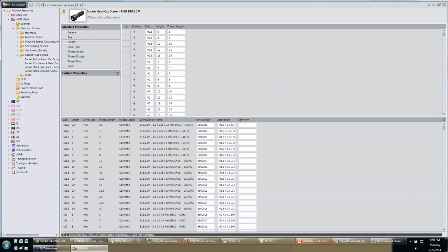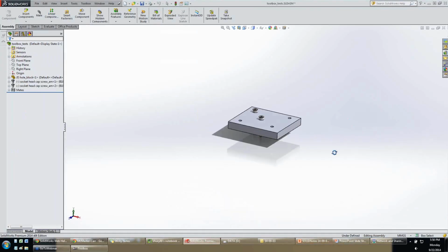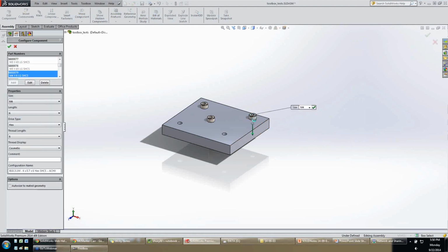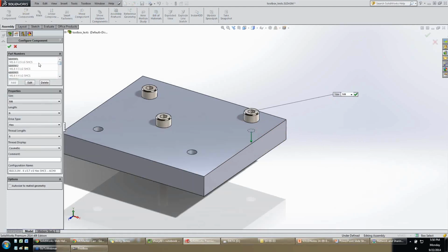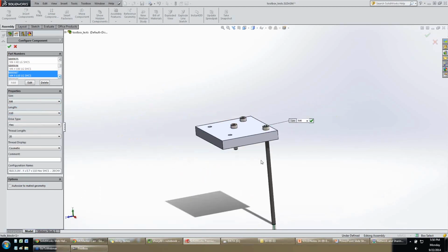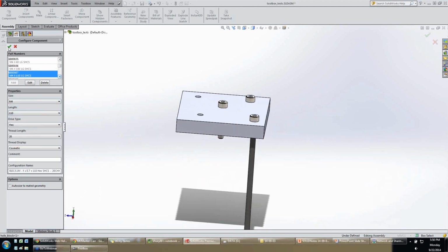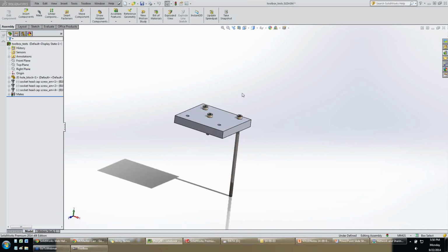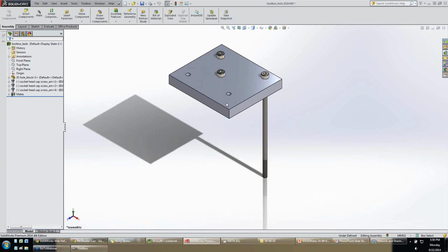So now if I go ahead and jump back into SolidWorks, and I bring another Toolbox component in, we can see up here it lists all the part numbers, all the descriptions, everything that we gave part numbers and descriptions to. We can even see the thread display is now limited to cosmetic. The drive type is limited to hex. For M4 by 110, it's now a selection that we can go in here and select. So all that is there for us. Real nice and easy.